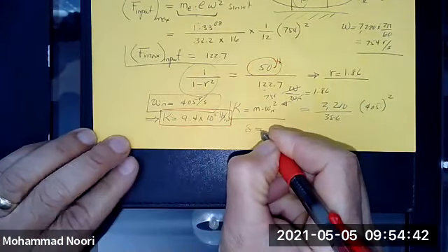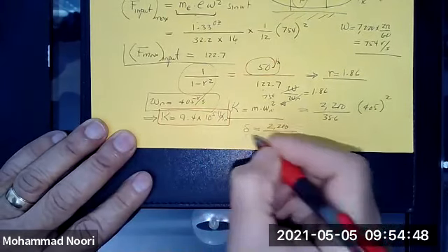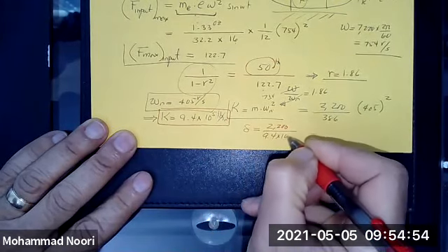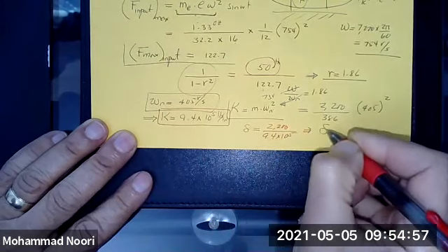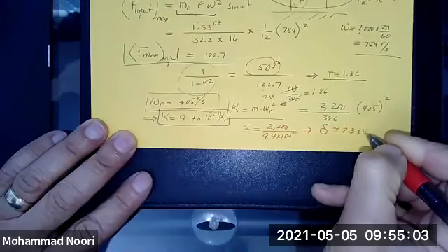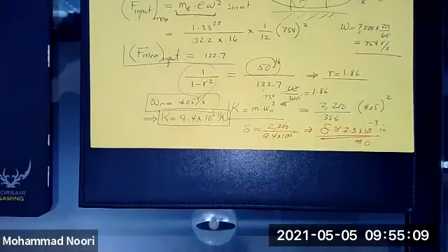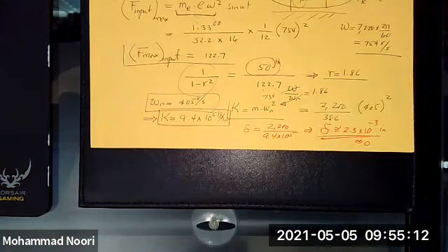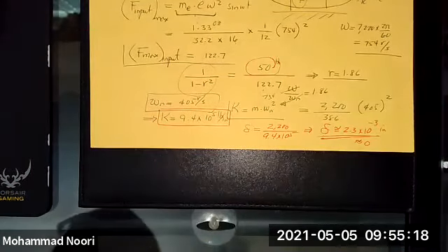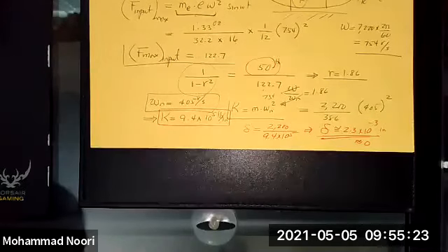The static displacement under that weight is W, the weight, divided by the stiffness, 9.4 times 10 to the 5, which gives me a static displacement of roughly 2.3 times 10 to the negative 3 inches, which is almost zero. So this is a good stiffness value to use to keep the force transmitted to less than 50 pounds.